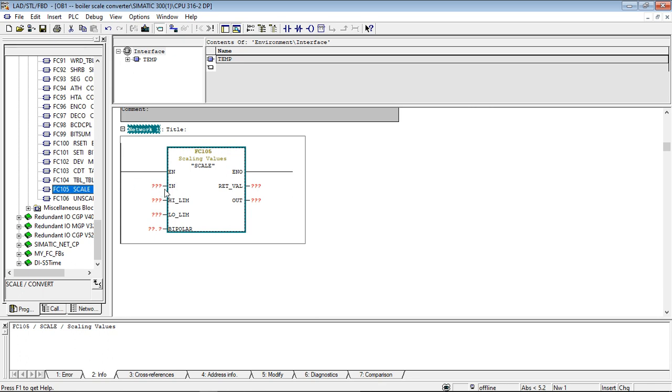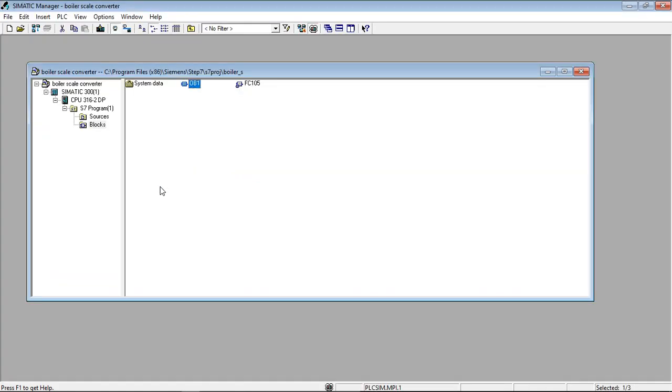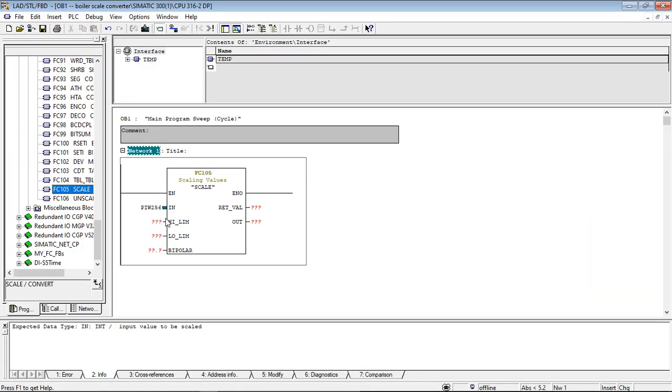This is the address of your analog signal, the address where you put your analog signal on the analog input module, which is 256. That's the first one we are using. There are other ones that you can use, but we are using 256. The other addresses that you can use, if you want more explanation on that, you comment.